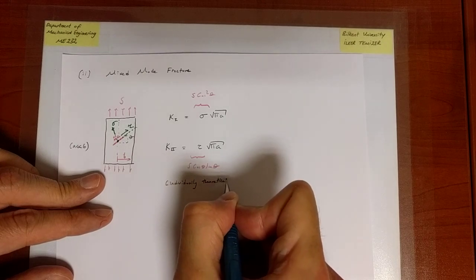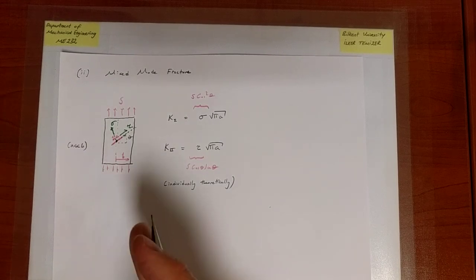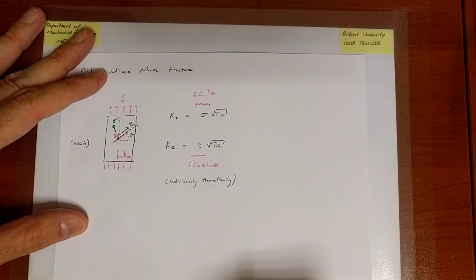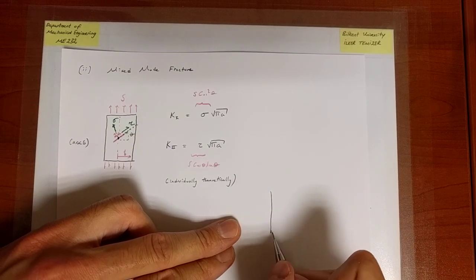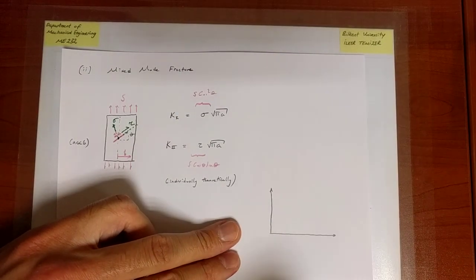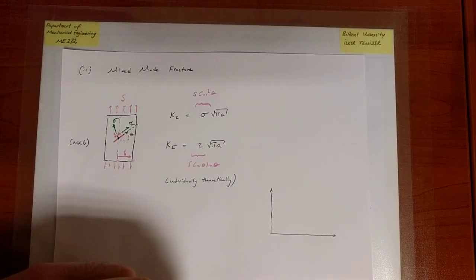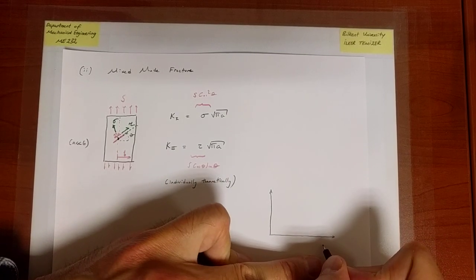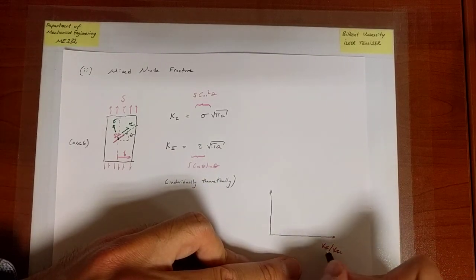but if I would like to decide whether failure occurs or not, ultimately, just like looking at multi-axial failure criteria, I have to do experiments. So, well, how can I do experiments? Well, something simple that you can do, just like we've partially discussed in the case of failure criteria, is very well controlled experiments. I have two parameters, a K1 and a K2. And I know that if this is, let's say, the K1 axis, I will scale it by K1C, the fracture toughness for mode 1.